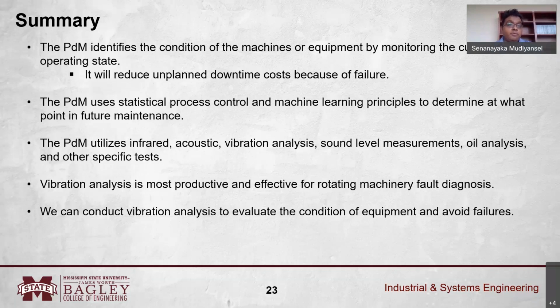PDM identifies the condition of the machines or equipment by monitoring the current operating state, so it will reduce unplanned downtime or breakdown cost. PDM uses statistical process control and machine learning principles to determine what type of failure is going to happen, or at what point in the future maintenance is needed.